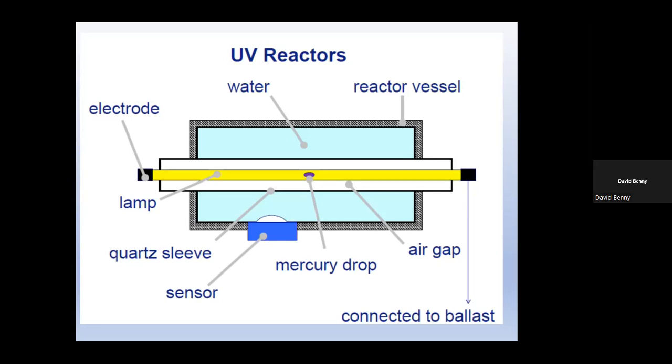Now, if it's a simple in-pipe system, it's regulated based on the flow requirements that the manufacturer would have given. And UV systems, if you're looking at wastewater design, are always supposed to be designed for peak flows. That is something that most consultants do not always take into consideration.